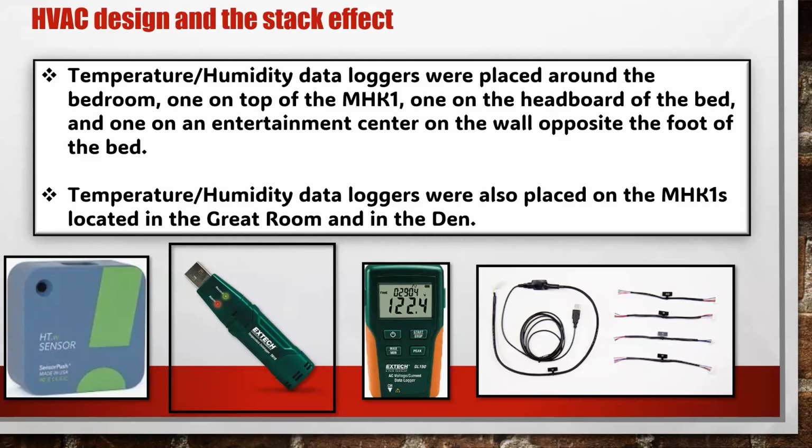Yeah, I've had contractors do lath and plaster walls. If you don't put my unit level or flat, then you put stresses on points in the unit that shouldn't have stresses, and things wear out faster, like wall head units, the bearings in the blower. They'll wear out faster if they're twisted when you mount them to the wall. But I have some contractors who will mount a sheet of plywood and shim it, and then around the plywood they will put trim, tapered to cover all the holes. It looks pretty cool. They do a good job with it, and at least they get the unit flat.